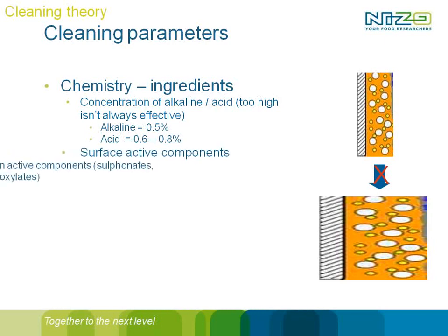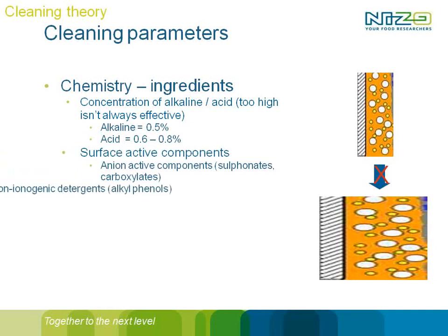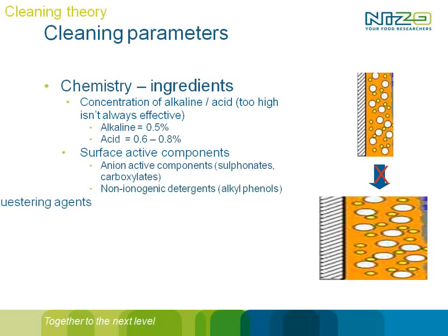In addition to the standard alkaline and acid, you do have other components, for example surface active components that make it easier to attach to the fouling. You have what we call sequestering agents that can bind specifically to, for example, calcium. EDTA is a very well-known example of that.